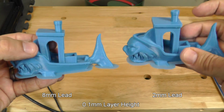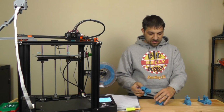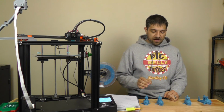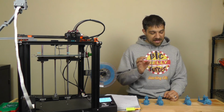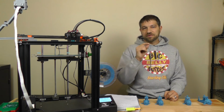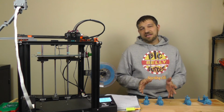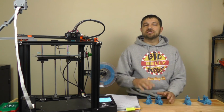Again, this is only a sample set of 4, 2 per lead screw, and so it's nothing scientific, but I think it's a marginally good upgrade if you were looking for accuracy. When Chuck Hellebach did this using his magic numbers video, he said that the differences in quality he noticed were more at the microscopic level, more with layer consistency if you look at it really close. I don't have a microscope to take a look at these, but I think even subjectively at a macroscopic level, it's a marginally better print.